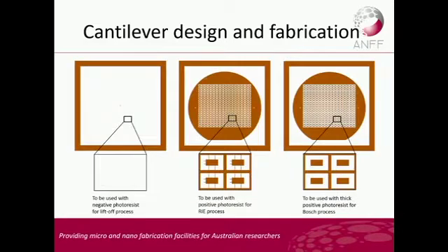So then we can generate 3 masks. Here are the 3 masks. This is what they look like after we've printed them off. There's not much to see on the first mask, because it's just 50 micron gold dots that appear up here. And then this part here is what defines the top. This is the top of the wafer. When we generate the device, this is the top, so it shows the cantilever arms there.